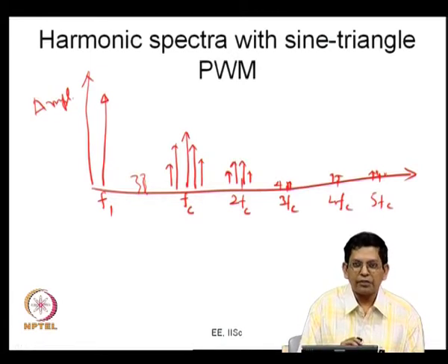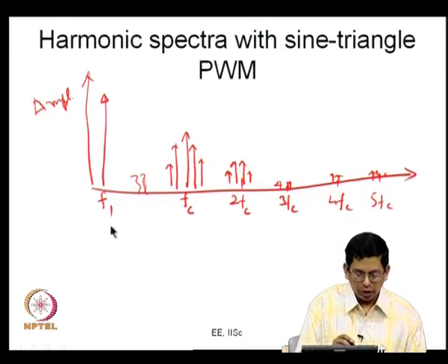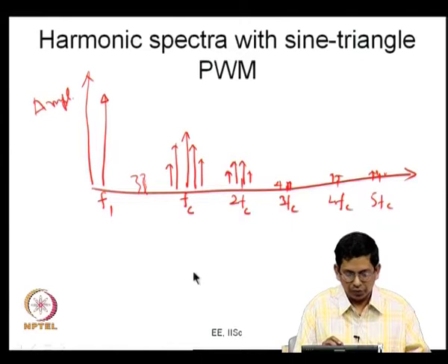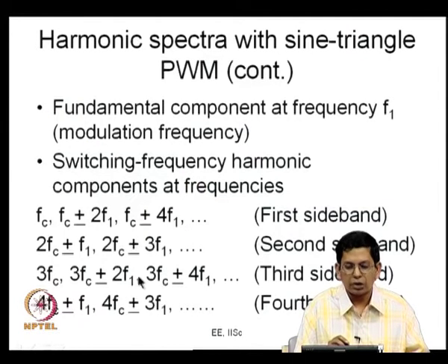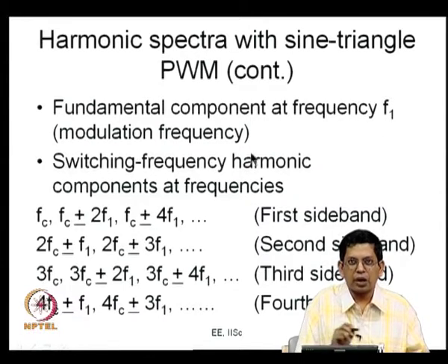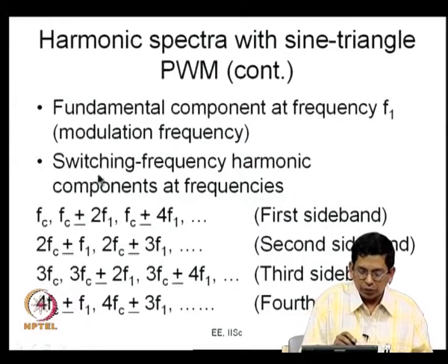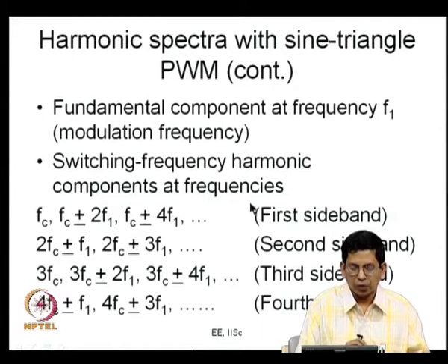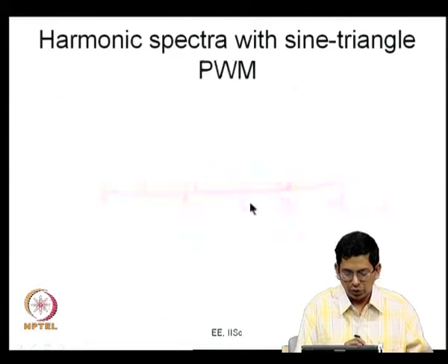This is only to get a feel for how the PWM spectrum would look now. To get more into the specifics, what you have here is the fundamental component at frequency F1, which is the modulation frequency. Then you have the switching frequency harmonic components.